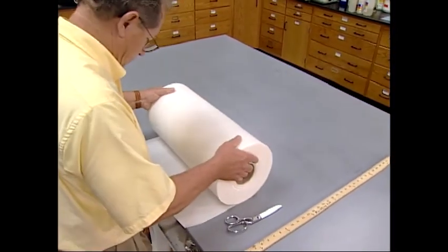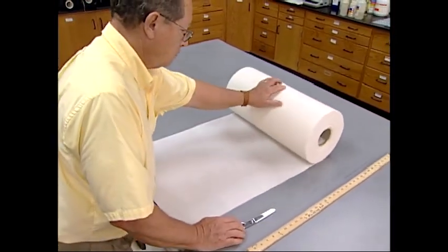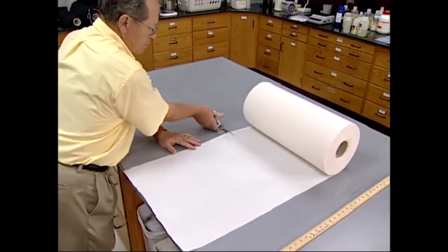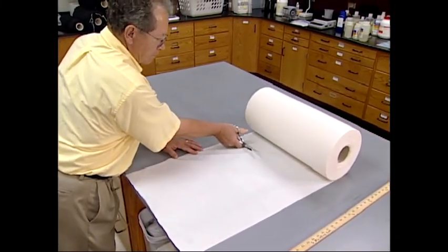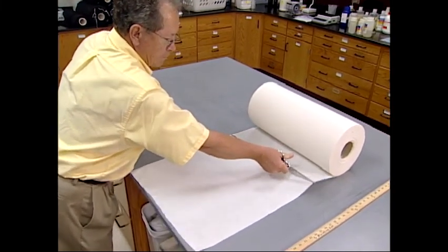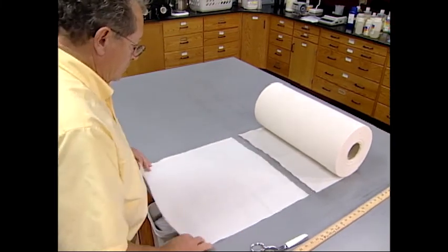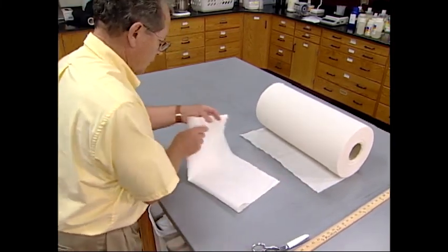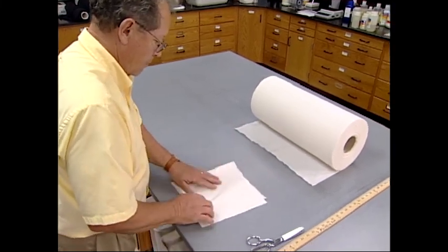Option D is intended for use with narrow fabrics as designated by the trade. These fabrics are usually 300 millimeters, 12 inches in width or less, have a selvage on both sides, and are woven on multi-shuttle looms. The weighing system for these fabrics is not covered in this CD. However, the detailed ASTM test method thoroughly covers this method.